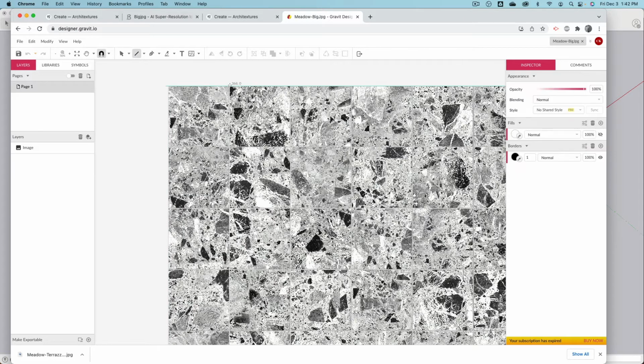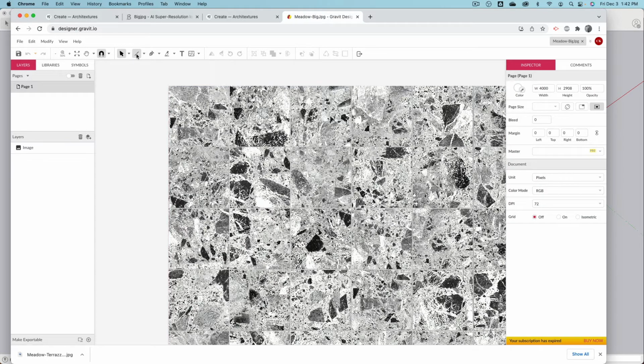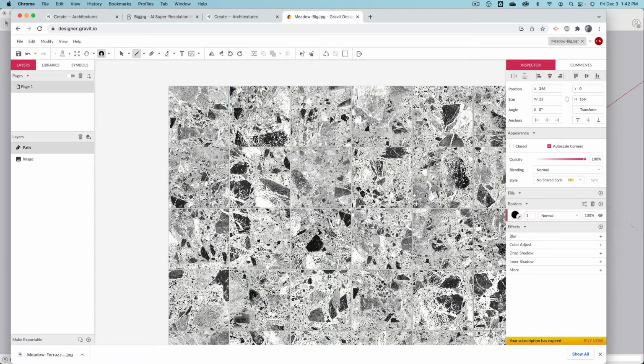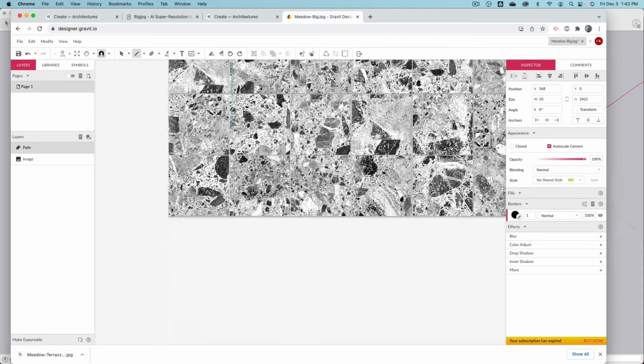Wait, sorry, line command, click. Oh, click and drag, my fault. Different program, different behavior. I'm clicking and dragging, holding shift, and then you see that it's vertical. I go to here, and you see there's a snap line. Release, and there's our line. Beautiful. There's our path.